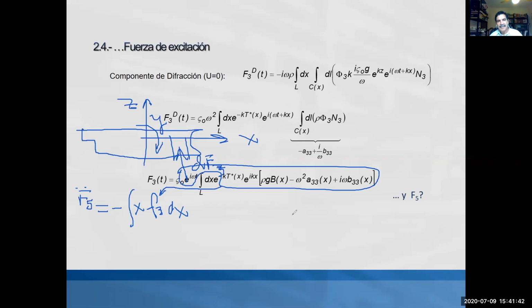You see that the two problems are very well related. You have force per unit length times dx, that gives you dF3, times an arm that gives you a moment. But you need this negative because the action of this force will try to rotate in the opposite direction, the negative direction.